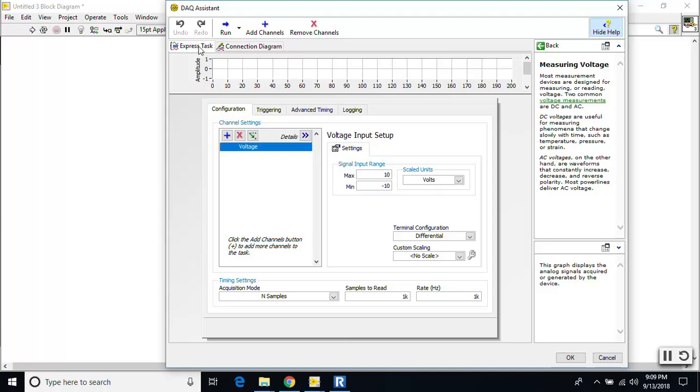Now there are a number of important things here. Let's start here. The voltage input. So this is the input range. And the lab handout is very specific about what signal we're going to give you. You need to set up your DAC so that it covers a specific range.